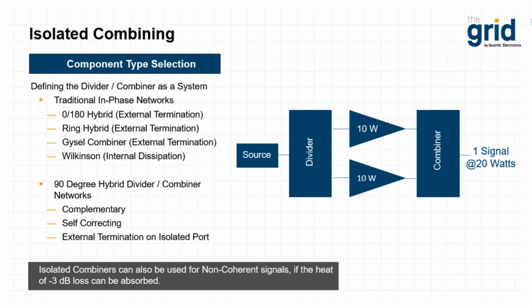If we're going to use something like a Wilkinson power divider, those terminations are internal, and because of the structure of the way that those power dividers are designed, there's usually a very poor thermal path with those to ground, and therefore I will caution against using a Wilkinson as a high power combiner because it really won't work that well at dissipating that combining heat.